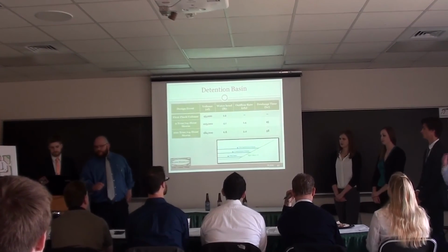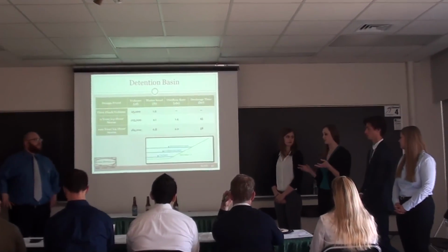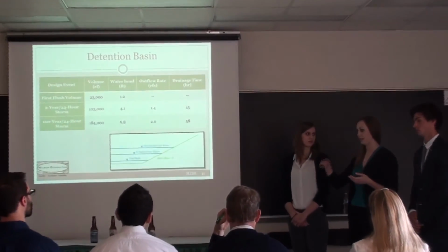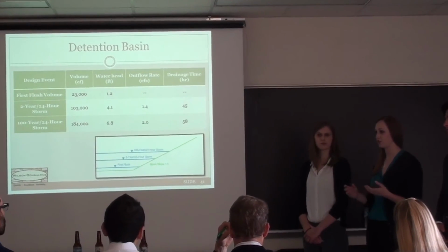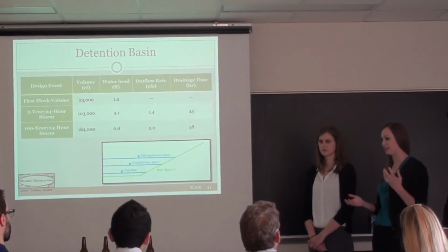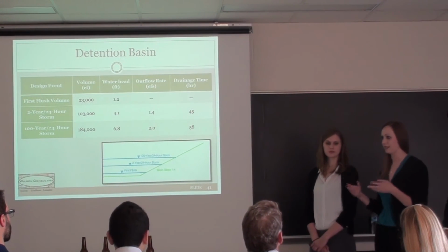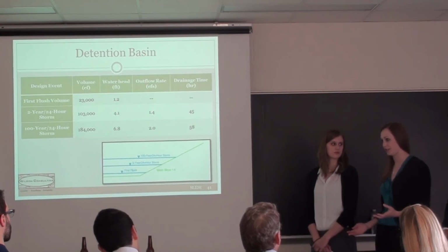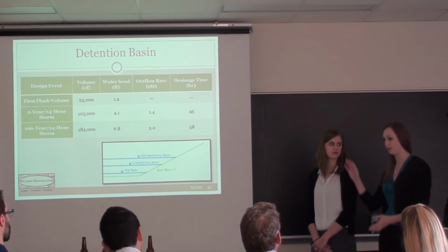Yes. How's it going to be permanent? How do you make it permanent? Well, the drainage outlet pipe is just above the elevation. Okay. That is from the volume of the first flush, and I got this design from the MDOT Drainage Manual, Chapter 8. That permanent pool will remain there. It may go into a little bit of infiltration processes, but for the most part it will remain.